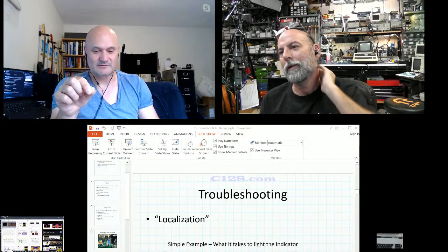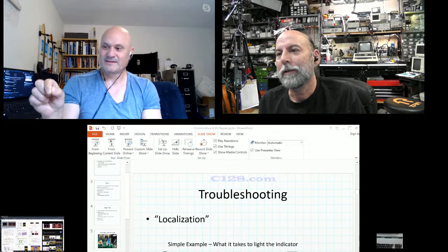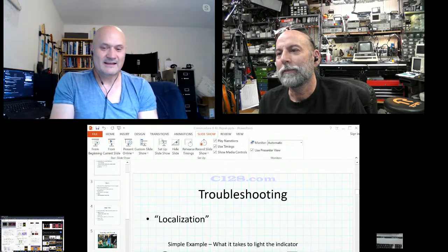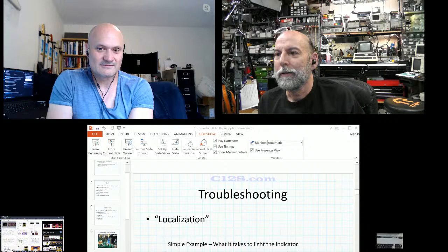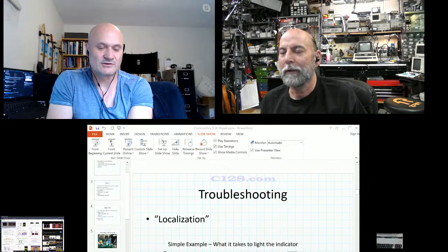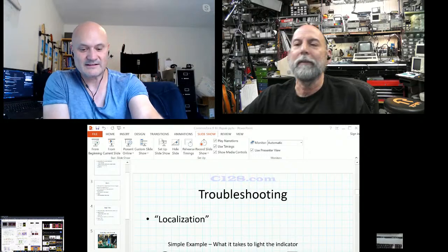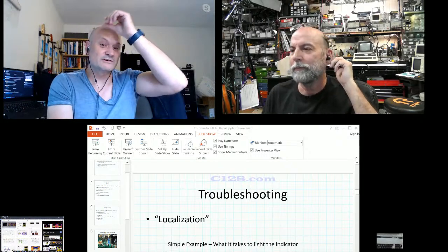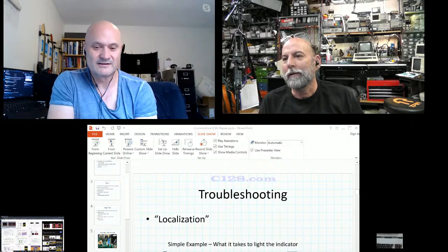Yep, that looks right. Next point, it's going to be clipped on one side. Yep. Next point, and you go through, and at some point you realize the signal I'm seeing there isn't normal. So something just in this region is crapped out, and then that's when you find your blown capacitor or your tantalum capacitor that's failed short.